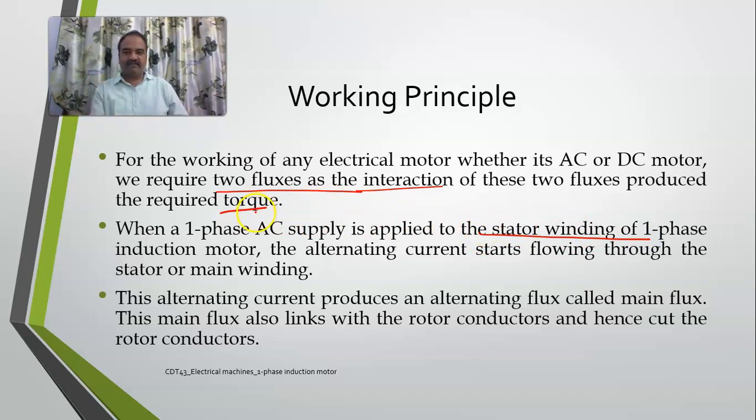So your stator is being given a single phase AC supply, and you will be getting only one AC flux. This AC current produces an alternating flux, which we call the main flux.